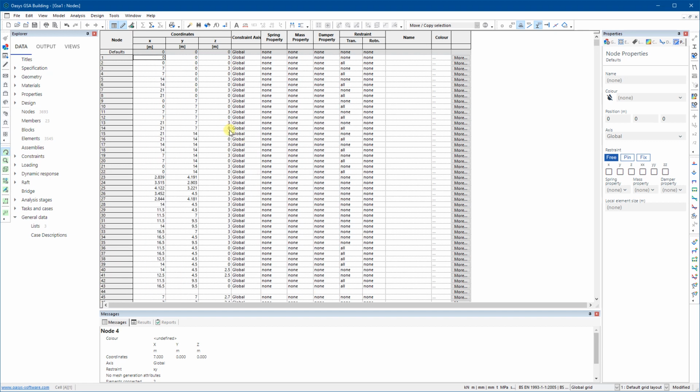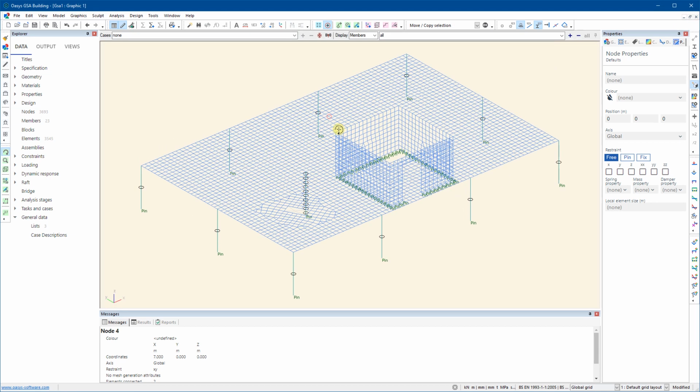So again, if you really had time, you could do a script to optimize the whole thing. And in reality, that's perhaps what we would do for a tall tower. We would use maybe Excel or Grasshopper and Rhino to actually create the model and then import it into GSA. Again, that's fine if you've got lots of time and practice, but you obviously don't have time. So this is a much more pragmatic way of approaching the problem if you just want to do a quick analysis. But back to applying loading.